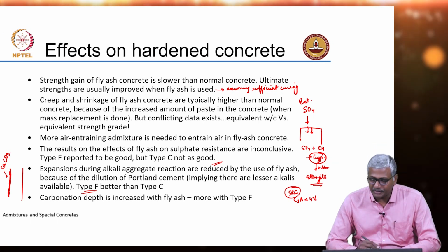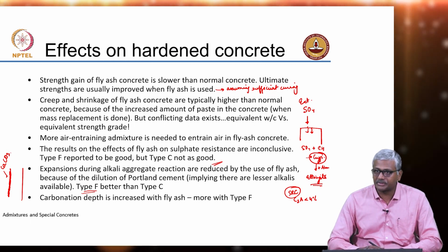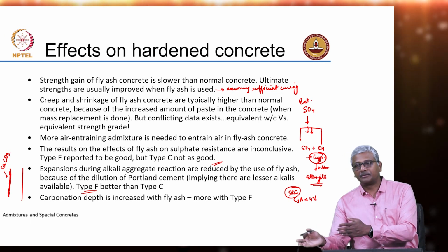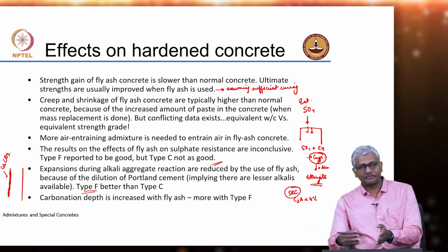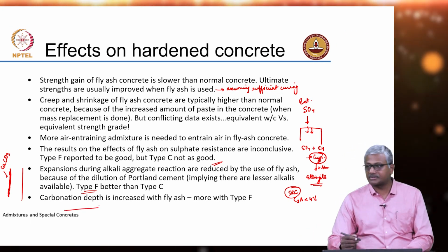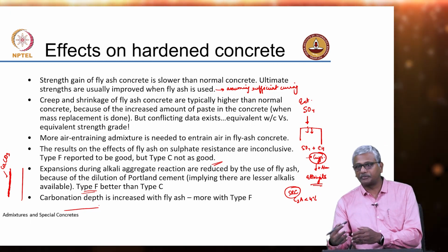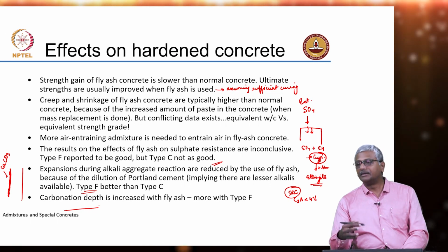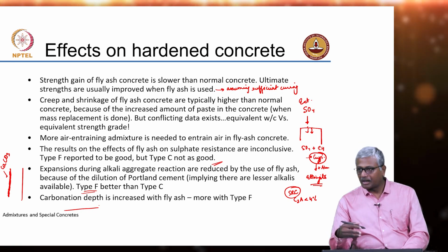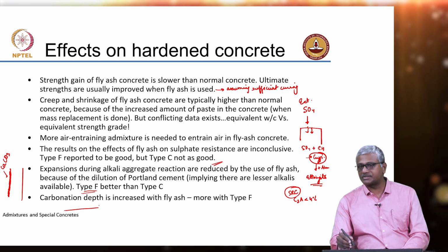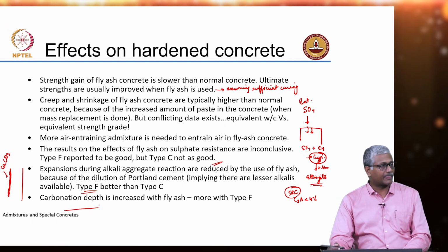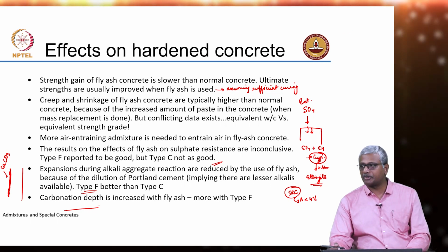So, that is one aspect that you will come across very often in discussions. So, when that line of defense went away, people started looking at the fact that carbonation gets increased with mineral additives, to stop the extra use of mineral additives in concrete. But again, this needs to be supported by hard evidence that indeed such concretes are more prone to corrosion, and that has not really been shown anywhere where blended cements have been used for a long time.